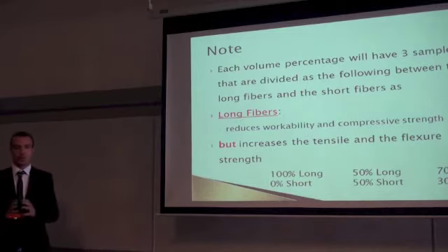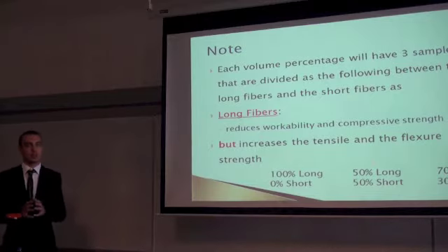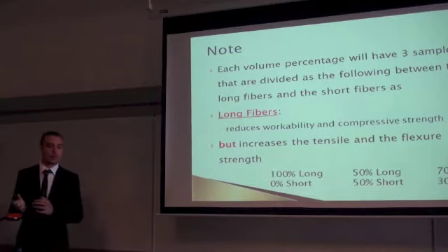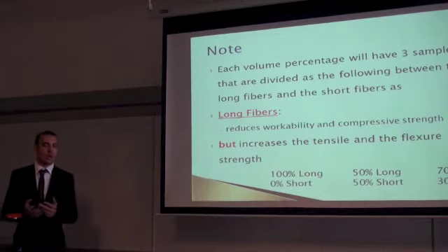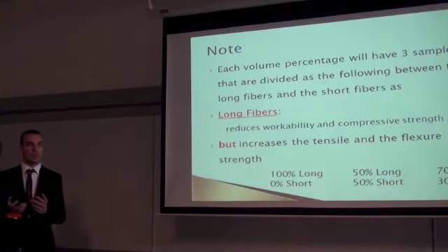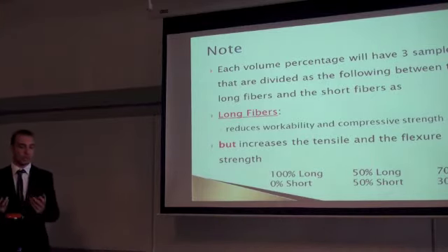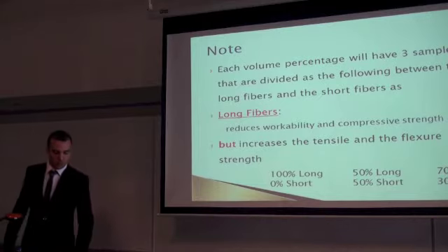And we decided to make the combination because the long fiber reduces workability and compressive strength while increasing the tensile strength and flexural strength. And the short fiber is doing the opposite. So we're trying to do the best after the two combination to get the best result.